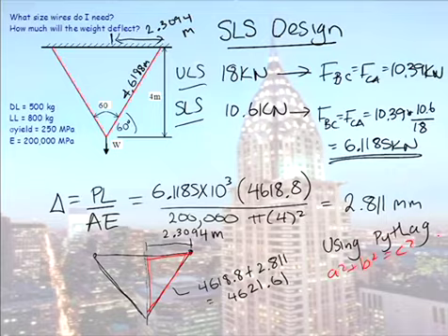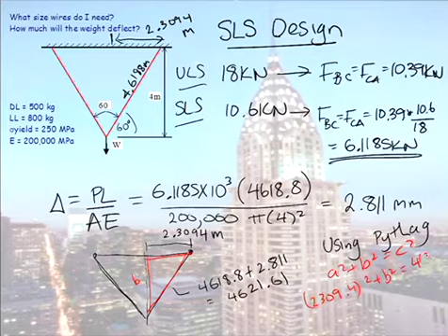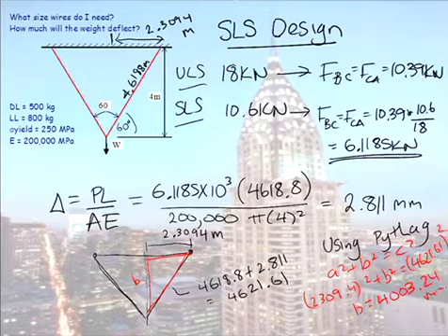I think you all know what I'm talking about. So if I call that b, a squared will be my horizontal length plus b squared is equal to my hypotenuse, and it is my lengthened hypotenuse. That will give me a b value in there of 4003.24 millimetres. What was that length originally? 4 metres. So therefore this thing here has dropped 3.24 millimetres.